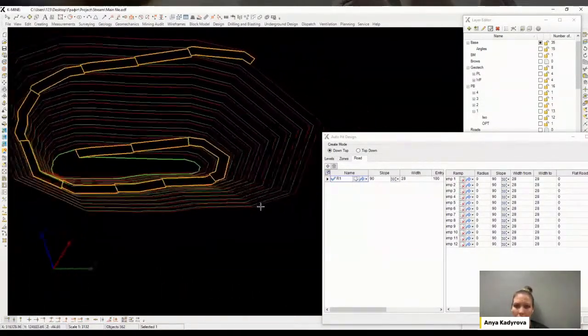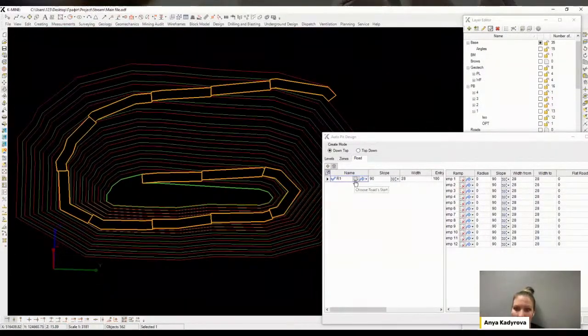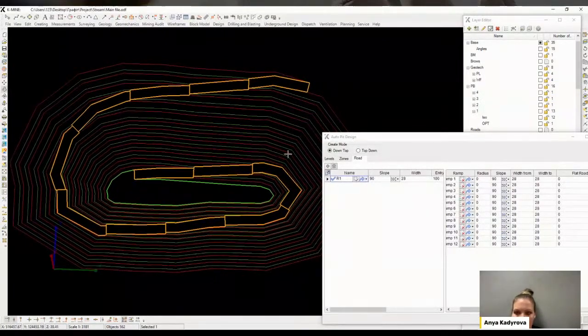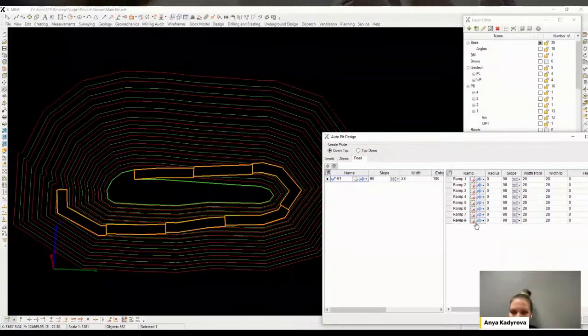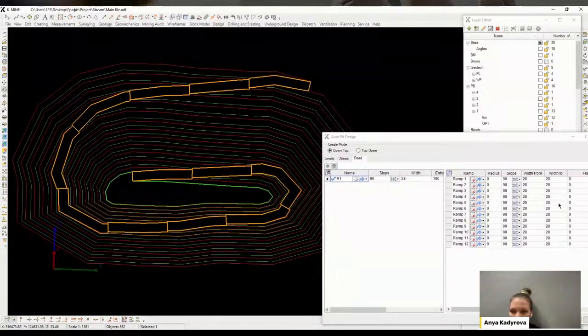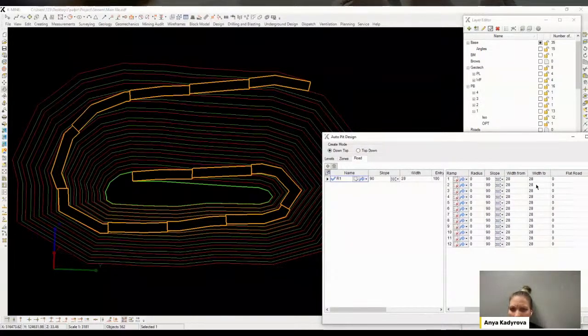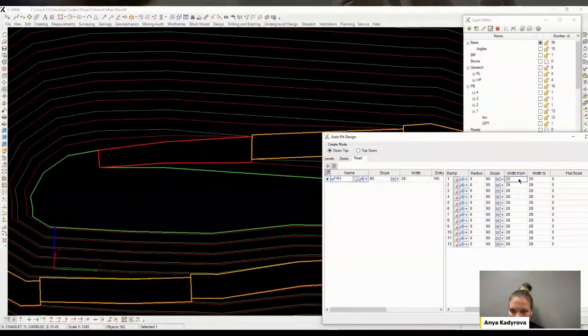Also, you can add horizontal inserts both automatically and in a specific place, simply by filling in the table. And the direction of the road can also be changed both as a whole and in part by adding a U-turn in a specific place. Adding turns is done automatically, like everything in this model. If you need to expand the turn, you can use additional features in the table, namely the radius column.